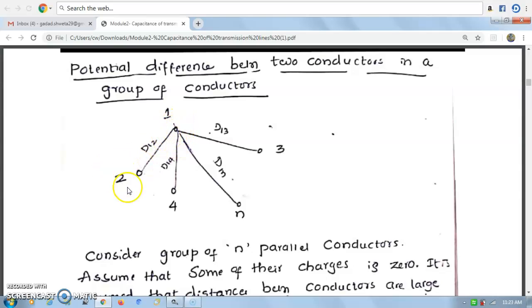Next, if you take the potential due to the second charge, it is the reverse of that: radius divided by distance. Next, the potential between 1 and 2 due to the third charge. Due to the third charge, what is the difference between 1 and 2? Q divided by 2 pi is common. Ln of distance, how to take? Second distance by first distance. For 1 to 2, which is the second distance here, 1 to 3 or 2 to 3?